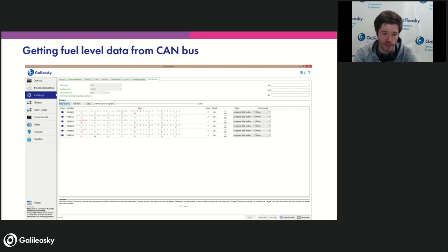The principle is basically the same as with the calculation table. You evaluate the current amount of fuel in the fuel tank, look for values in the CAN bus that more or less fit this value. Then, for example, add some fuel, check what values changed when you were adding it, and so on. So the CAN scanner is a powerful tool that allows you to find different data in real time, and fuel level is just one of them. That's not the only one.